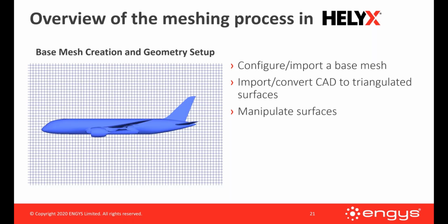So we have the facility within the GUI in order to manipulate these different surfaces very effectively to generate boundary conditions or cell zones, something like that. So this background mesh represents the coarsest cells in the system, and we're going to label this as level 0. All right.